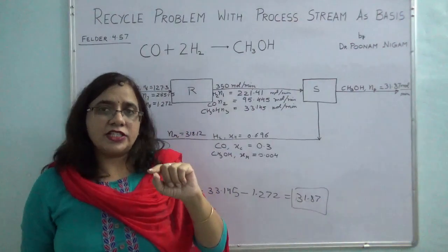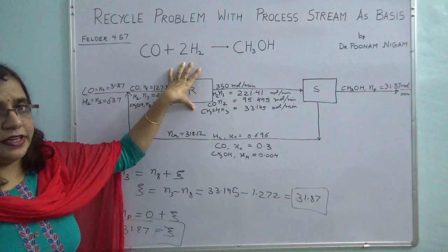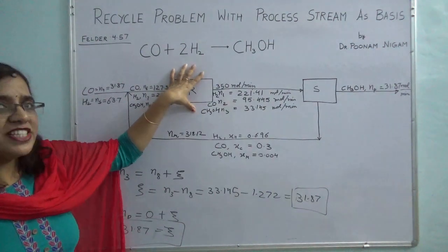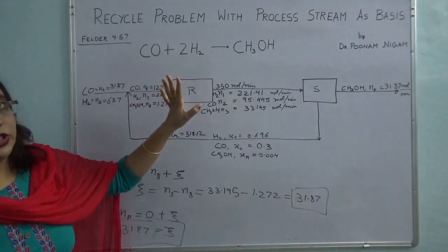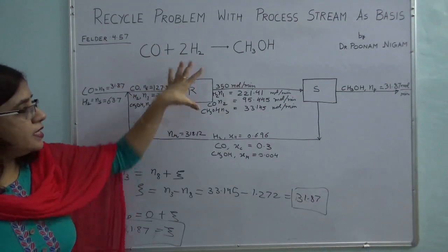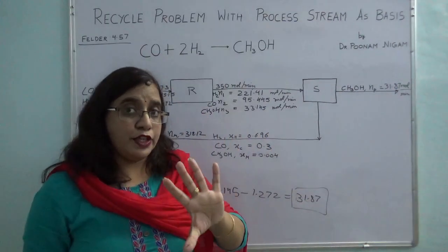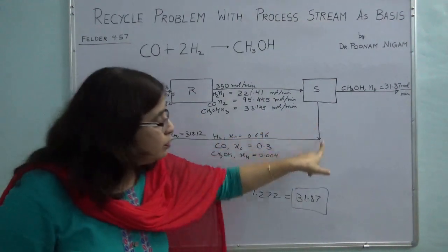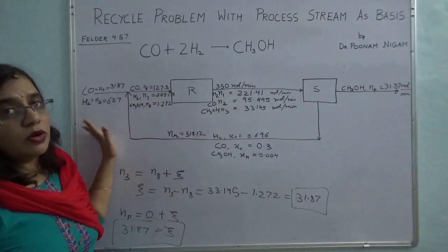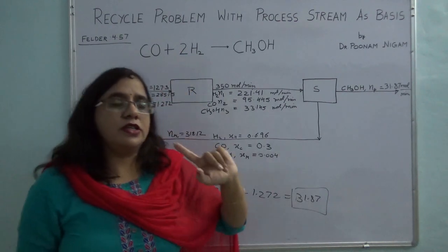The extent of reaction, basically, is information about the reaction itself. So how much reaction is taking place within this reactor, that is not going to change. Fine. So that's why it is a function only of the reaction kinetics and thermodynamics. So it is fixed. How many moles are reacting is fixed, whether you recycle it or not. But your conversion changes, while your extent of reaction remains the same.